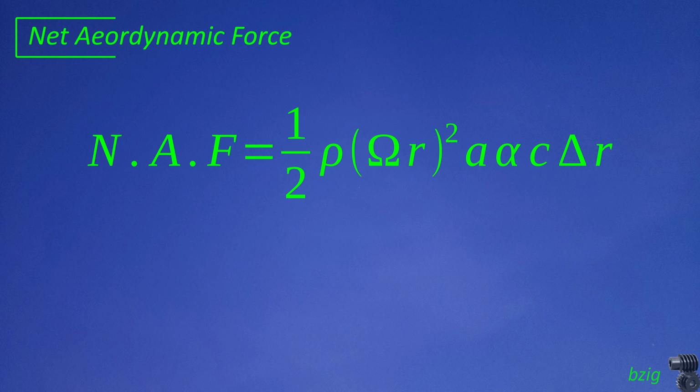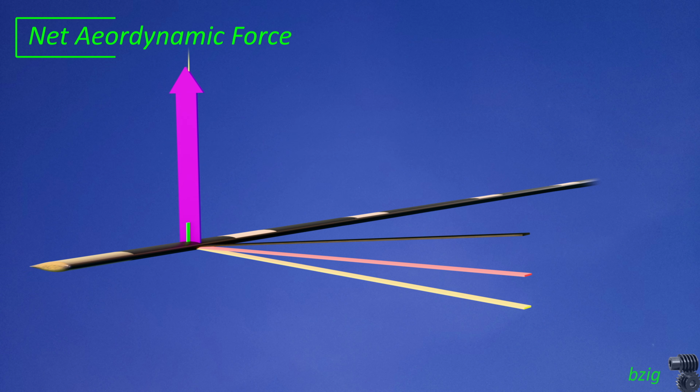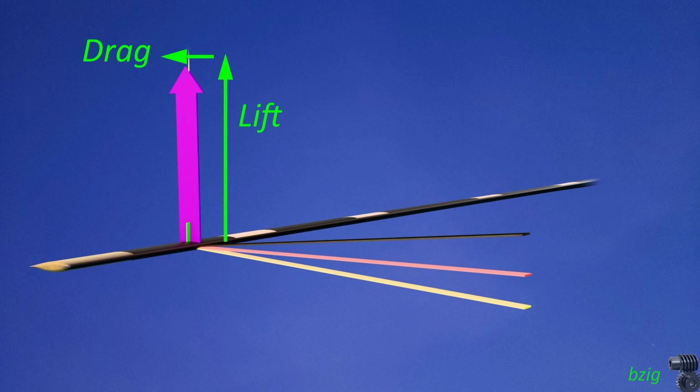The equation on the screen considers air density, rotor speed, radial position along the blade, the lift curve slope of the NACA 63-015 airfoil, the blade section angle of attack, and the area of the blade element, and the result is the net force at each section. The vertical component of this force is lift, and the horizontal component is induced drag.